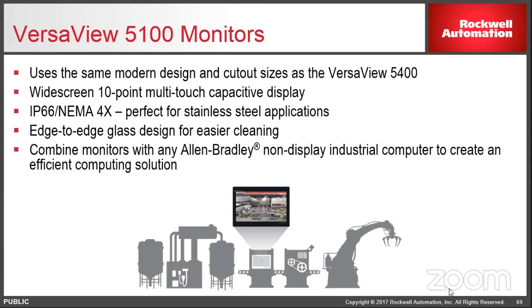All the monitors, all the panel PCs, and all the panel ThinManager thin clients use the same displays, so it's a consistent design across all of them. The monitors are IP66 NEMA 4X with a stainless steel band around behind the glass, so it actually is a stainless type product, which works if you don't need to do caustic wash down. We don't necessarily make you buy a stainless steel model anymore. It's all just built in for these. Those will pair up with pretty much any computer or computer-like device, and you pop it in your panel and you're good to go.